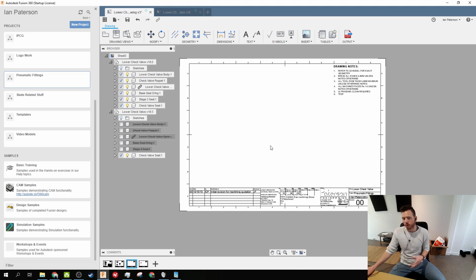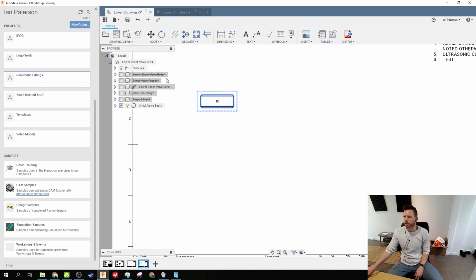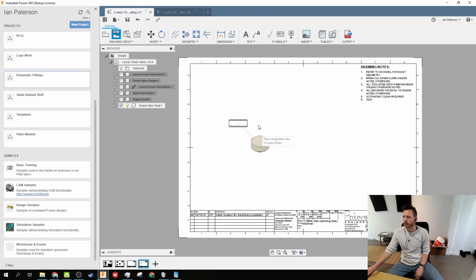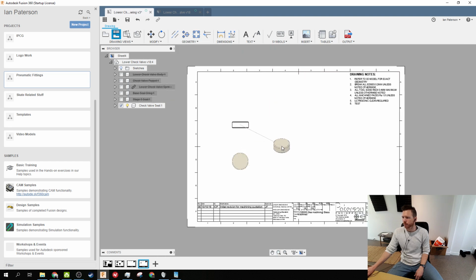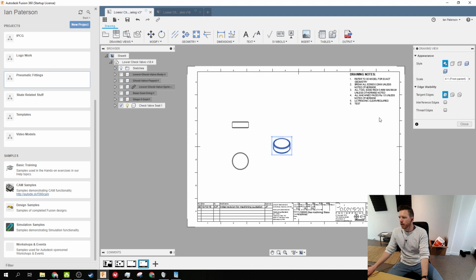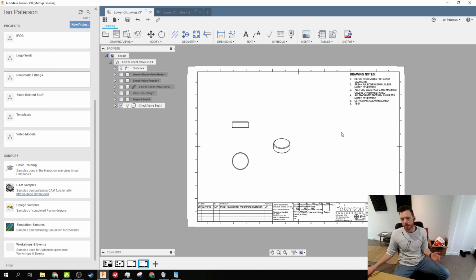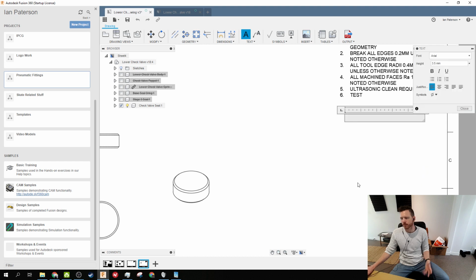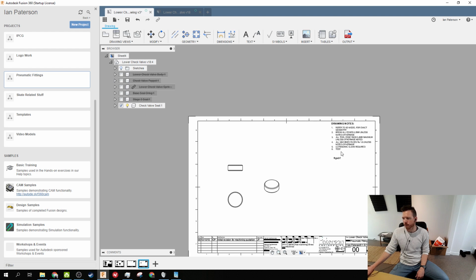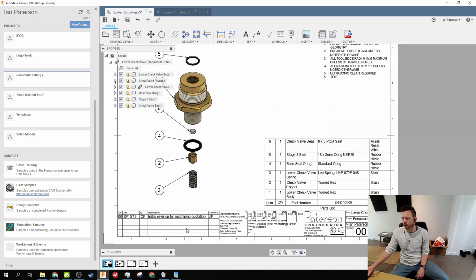What else? If you want to add notes to a specific sheet, like say this part would likely be a machined plastic part, and it will need maybe a different surface finish or a different tolerance on something, and you want to add a note to it, just use a normal text note, which is a bit ugly, but honestly it's just the best way. Just add a note there, and that's the best way to make sure it's just here and not on every other sheet.